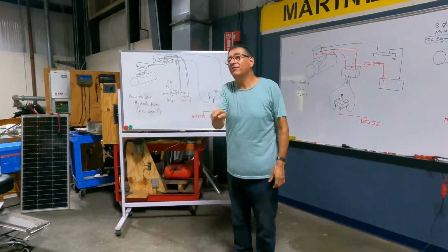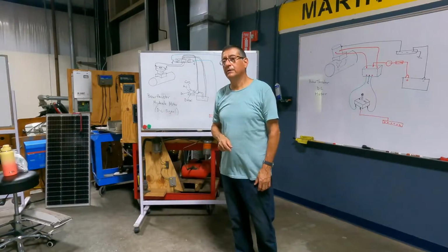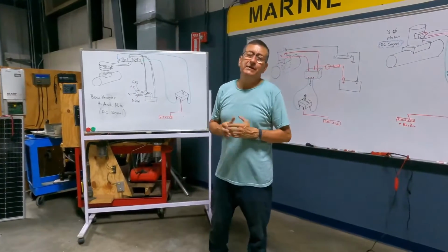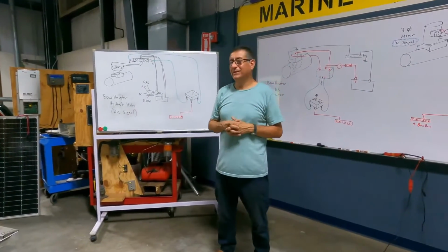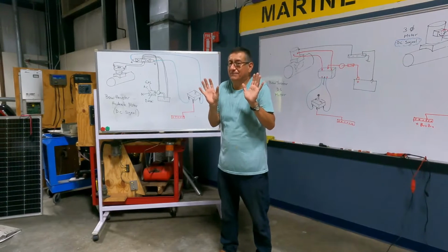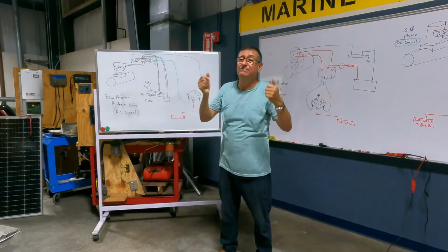Probably you have a leak over there, in that area. Can you have pressure gauges for each line? You can, but normally no. And those areas are difficult because you don't know where the leak is. Yeah, at least you know there's a leak on one line. You need to remove the sealing.